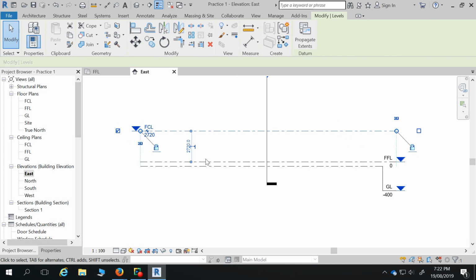Okay, so it depends on what we're drawing, how much we've got to fit on a sheet, where we want the level read from. It might be closer to one end of the building and not the other that we're using this level. For example, a parapet wall on a portico or something like that. It might be that your elevation's only showing it on that side. So there's no point in having the figure on this side and someone's got to come right across the sheet to see what that's associated with. So there's reasons that we might use either side. It's not a right nor a wrong. So that's what that does.